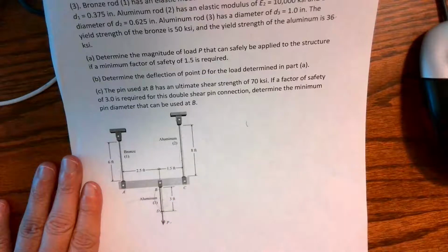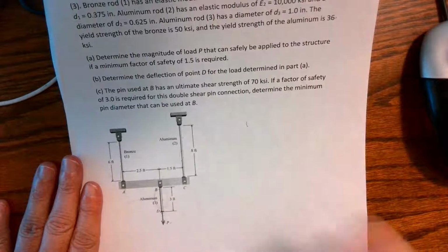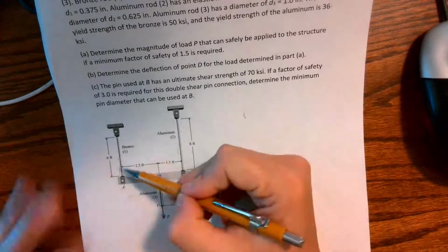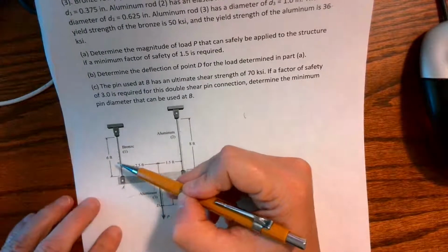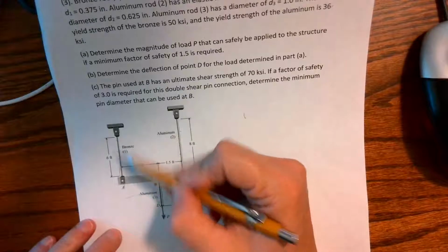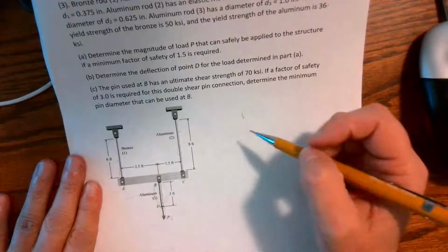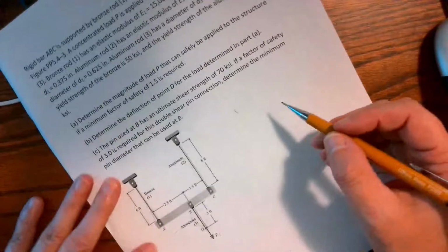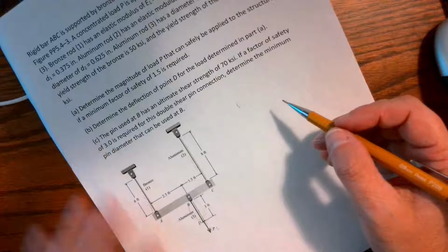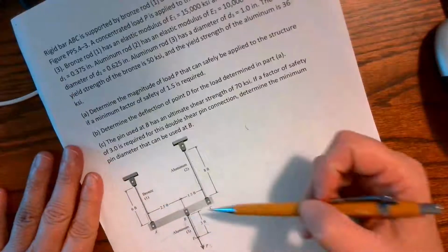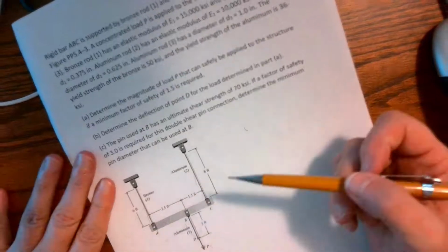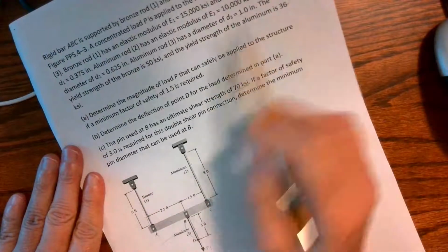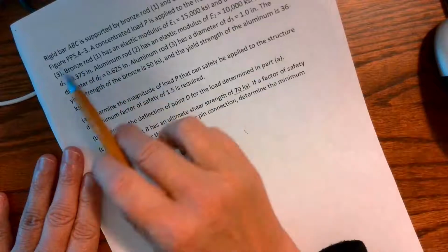And then I do the same thing down here. So when I find the force that causes failure in each of these, that's not P for the system, that's just the P in PL over AE for that member. So it's a step-through process. Again, I like to write down my information and change all of my units. If I'm in foot, pound, second, I like to be in inches, and pounds or kips, because usually my stresses are in KSI. So we're going to start at the top.